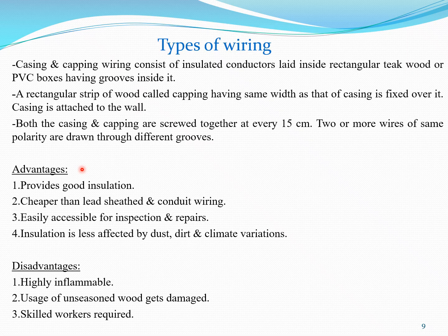So the advantages of the casing capping type of wiring: it provides good insulation. It is cheaper than the lead sheathed and conduit wiring. It is easily accessible for inspection and repairs. Insulation is less affected by dust, dirt, and climate variations.